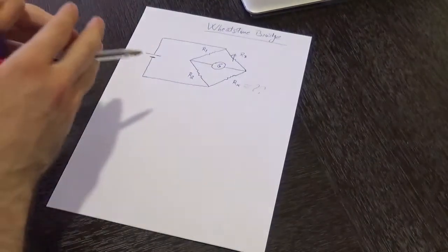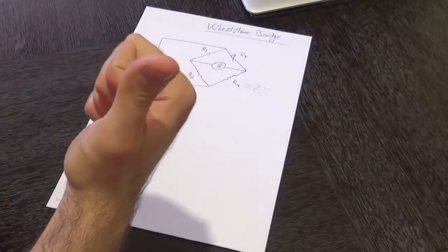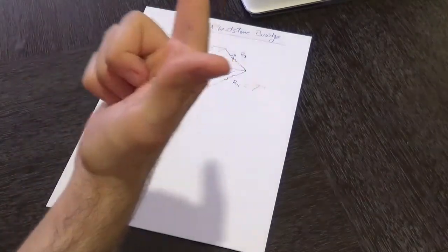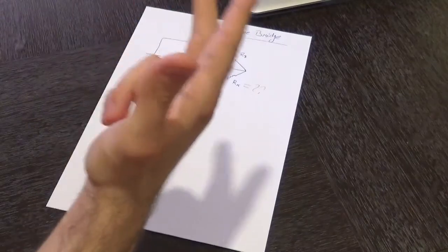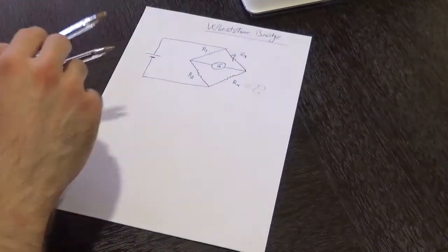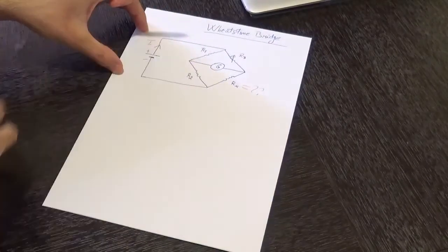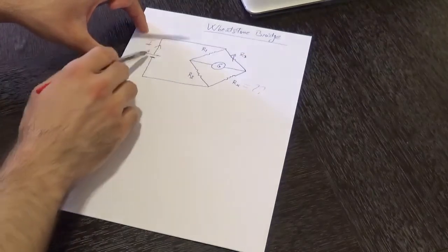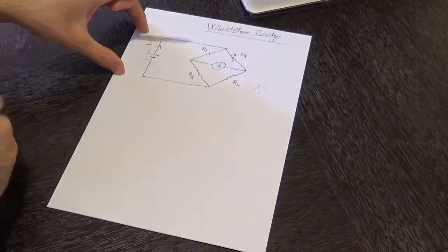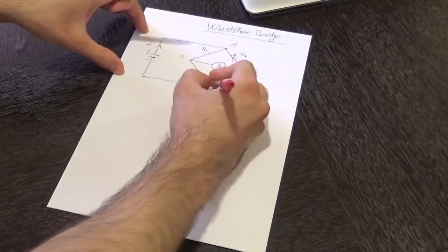So as we have seen before, in order to apply KCL and KVL, we need to consider first off a certain direction for the current. We need to be identifying the number of nodes that we have, and finally we need to be choosing a certain loop direction. So starting with the direction of the current. In that case, we are going to choose the positive conventional direction of the current, which is the one flowing out of the positive terminal. And over here we are going to name these intersections as A, B, C, and D.